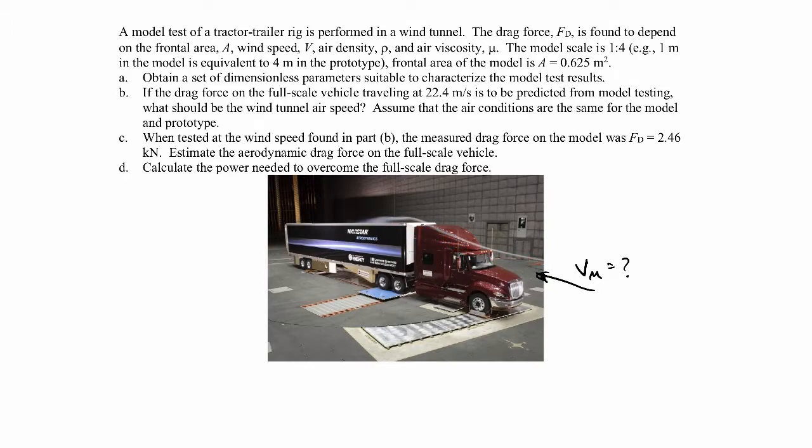And what kind of flow visualization is that? I'll let you think about it for a second. It's actually a streak line. If it's a steady flow, which it probably is in this situation, then it's equivalent to a streamline or a path line. But it's technically a streak line because it's tracing out all the fluid particles that passed through the end of the smoke wand that generated that streak line. Okay, well anyway, that's a different problem.